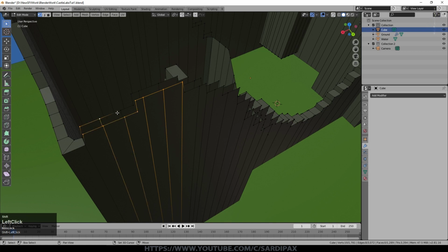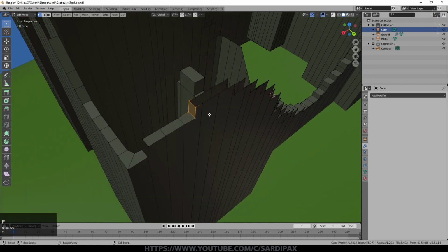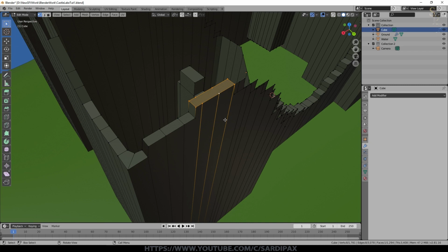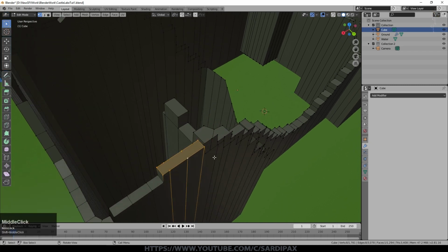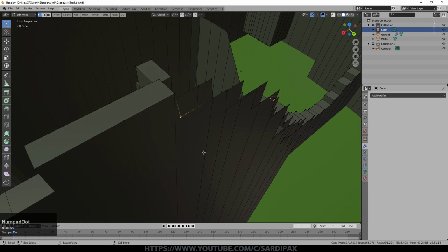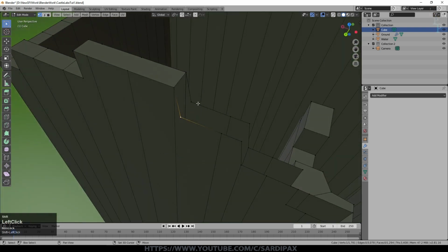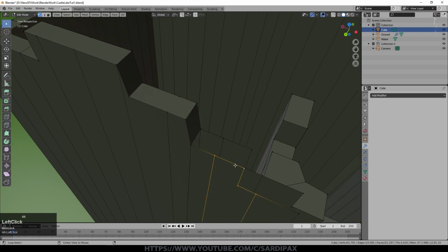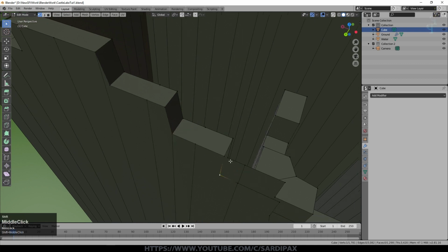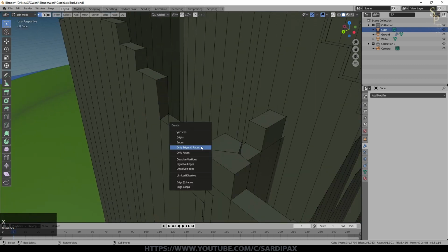You don't have to remove that dodgy geometry, of course. You could do the way I did it, which is just going along like this and just filling it as you go along. And you can just press F to fill, of course. You don't have to bridge. If you manage to select a whole length of vertices, or the whole ring of vertices on the inside and the outside, then bridge is what you want. You don't want to use fill. But if it's just a straight set like this, fill will be fine. But there you see it's going around a corner, so it can be a problem if you just use fill for that. I'll do a few more along this front edge, and so on.